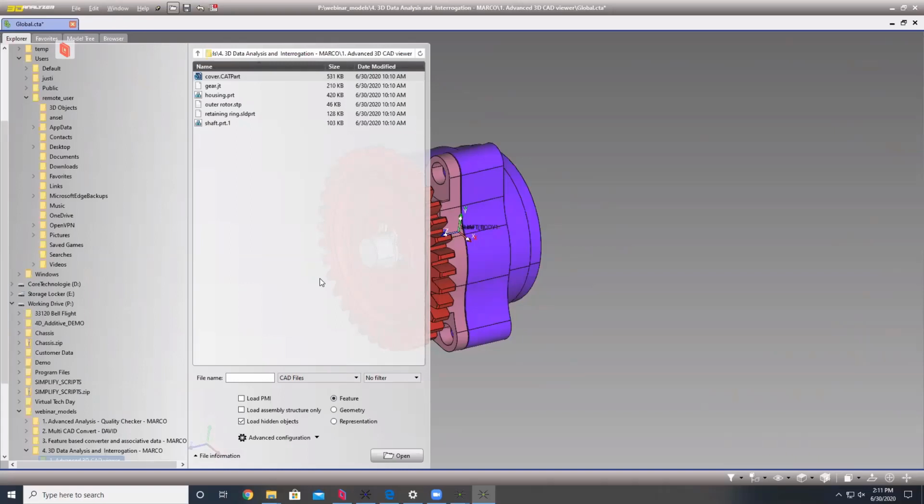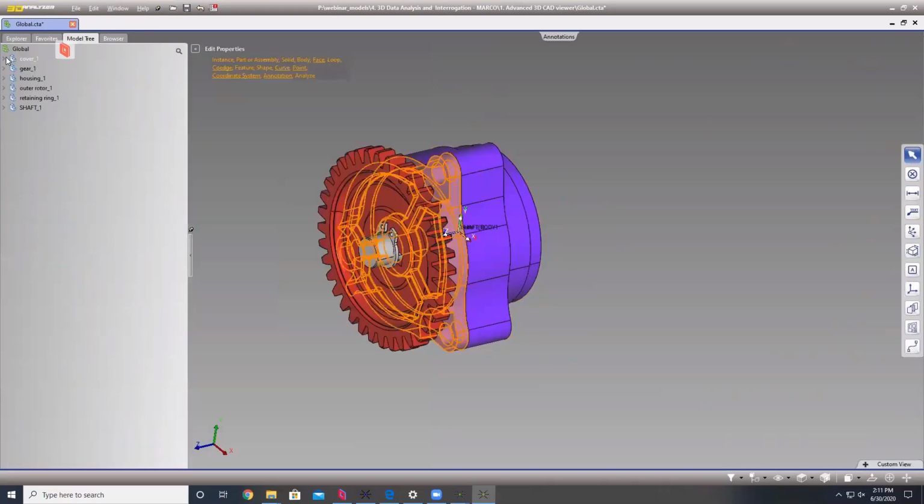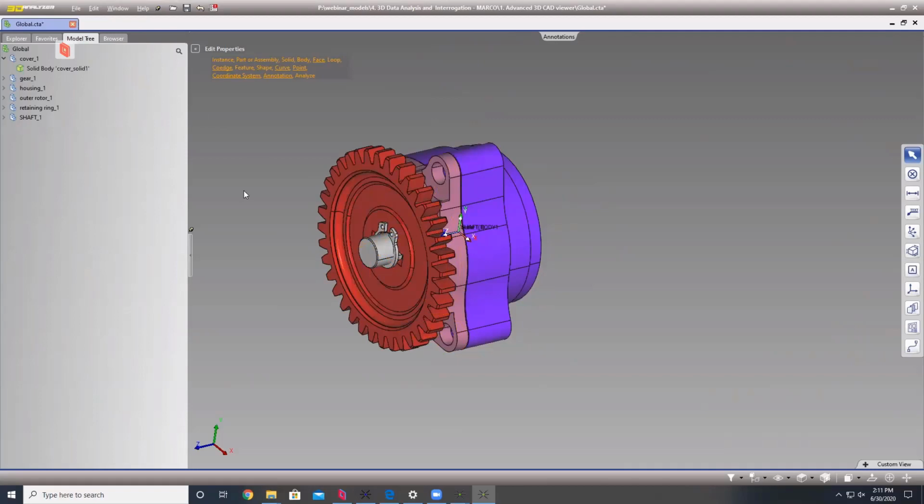the relationships between different parts, if it's an assembly, all of the features that make up the geometry, patterns, holes, sweeps, splines, all of that will be retained. So if you choose this mode, it will be loaded up as such, and you will see the history in here. Instead of just being a single icon representing the body, you see each one of the operations. And that will be a prerequisite for 3D Evolution in order to convert to another format in feature-based mode. That's another switch that we have.